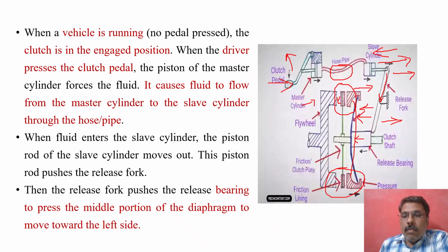So as compared with the frictional clutch, here you use a cylinder, and oil is used to execute the action of the clutch element. So it is entirely different from the frictional clutch. In the frictional clutch, we use the frictional force applied over the frictional surfaces by means of springing action.